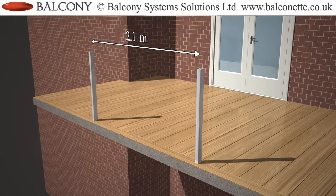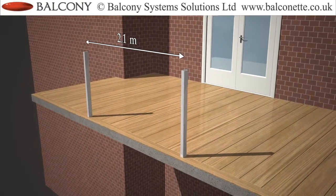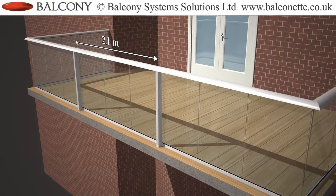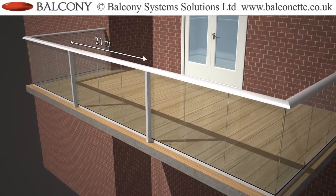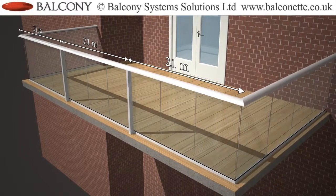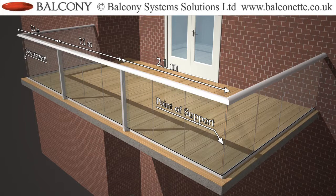The maximum post spacing allowed on Balcony 2 system with this type of post is 2.1 meters between post centers. This means that once the run surpasses 4 meters in length, posts must be introduced, and the maximum span between post centers can be 2.1 meters. Corner posts are not required, and the 2.1 meters can be measured from the corner, which is a point of support.